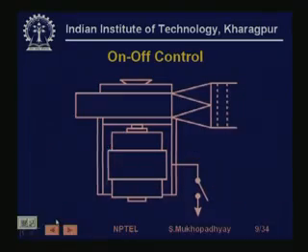Similarly, another major application for flow control is for cooling. If sometimes you send coolant and sometimes you do not send it, then the temperature on the equipment will be pulsating, and this may affect reaction rates, and it may cause thermal stress on the equipment. So in general, for industrial flow control problems, we cannot tolerate such pulsations. Therefore this on-off control method is not good. So we go for other methods. So what are the other methods?